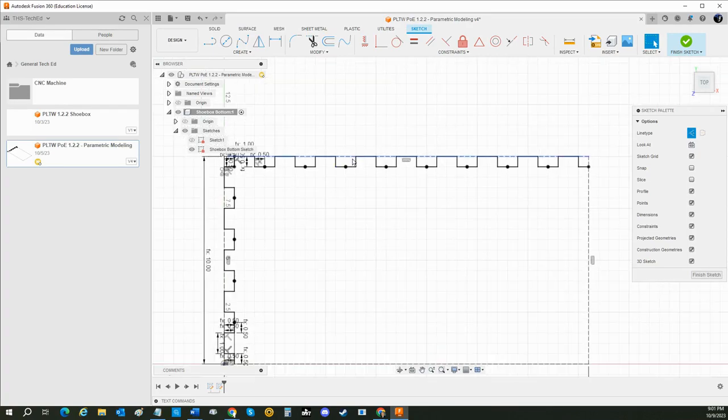But now that I have these two here, I'm going to shortcut this just a little bit. I'm going to put a construction line right at the midpoint of this thing. Looks like it's right. Actually, let's do it off this line because I don't have anything on it. Come down to find my triangle. There we go. I'm going to come straight up this side. And I'm going to do it again off this line here. I'm going to find my midpoint, come right across. All right. And now what I can do is just mirror these things.